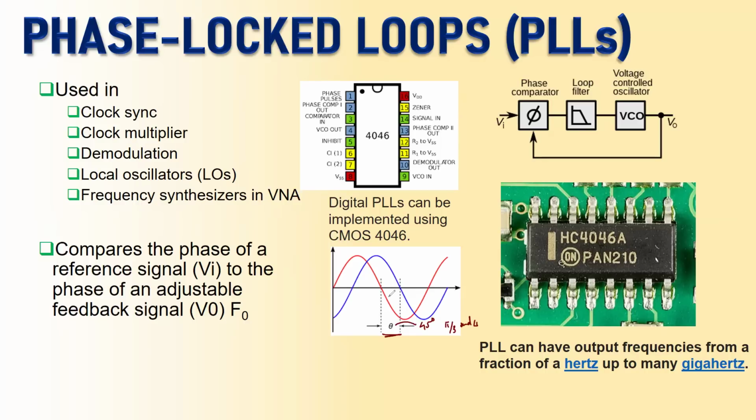So I say again, if there is a phase difference theta between the two signals, which can be 0 degrees or a finite value, for example 45 degrees or whatever the value, the job of the PLL is to lock and remain locked at this phase difference. If the phase difference is 0, it will make sure the phase difference always remains 0 between the two signals.